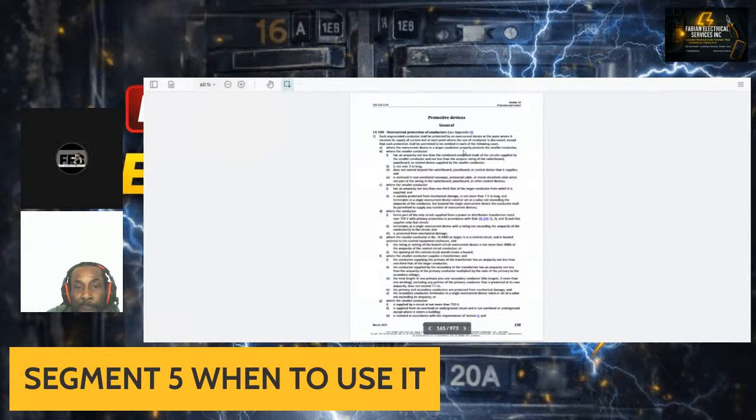Where the smaller conductor has an ampacity not less than the combined computed load of the circuit supplied by the smaller conductor and not less than the ampere rating of the switchboard, panel board, or control device supplied by the smaller conductor, is not over 3 meters long,